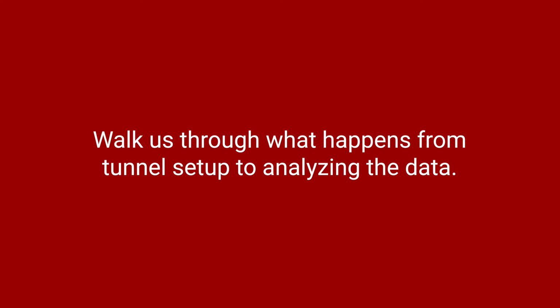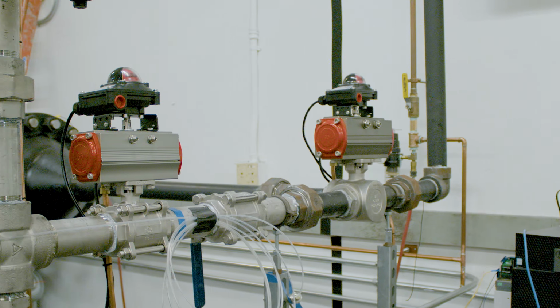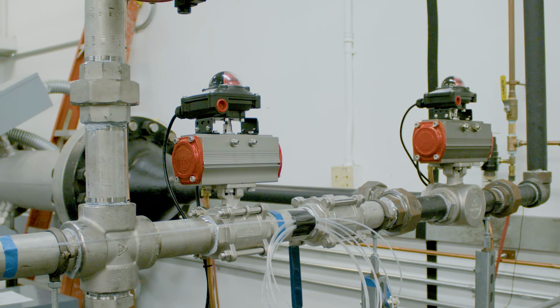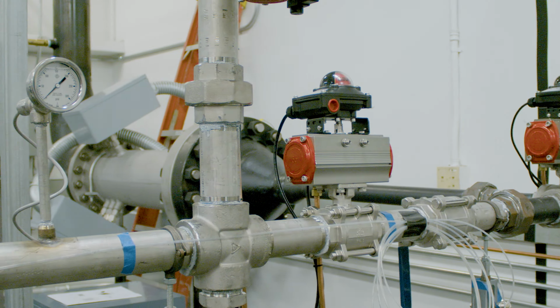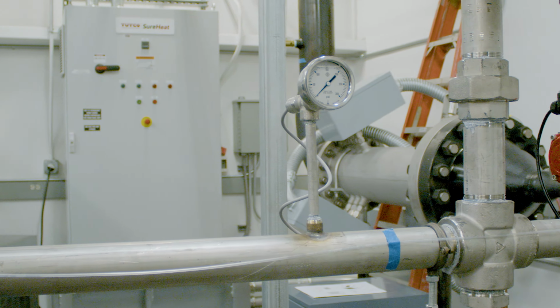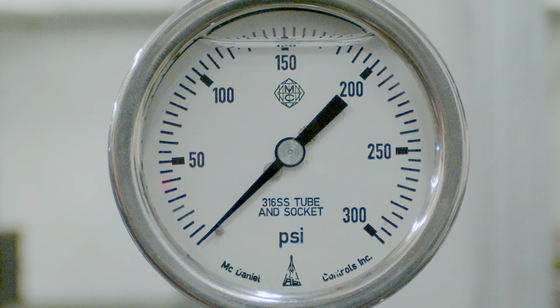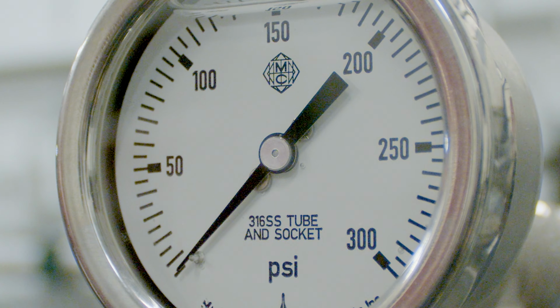Walk us through what happens from tunnel setup to analyzing the data. For running the wind tunnel, we have a valve that we can open and close and throttle in between from a computer. We open the valve to let high pressure air in from our compressor outside. That air then goes into the nozzle, which, due to its shape, causes the pressure of the airflow to drop. And when the pressure drops, the velocity increases according to something called Bernoulli's equation.